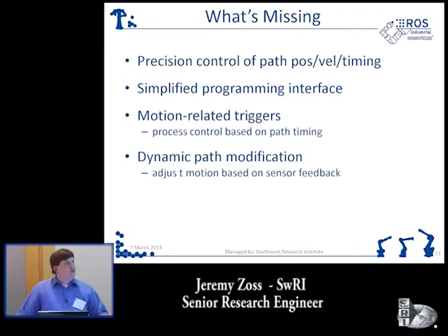You know, there's tools in ROS to really get in there and set constraints, but in some cases, they're kind of buried down in there. On a typical robot controller, it's right there. You say, here's my move command, and I want to move within this close of my termination point, or I want to maintain this velocity, or I want to move around a corner. There's all sorts of specific controls tailored to make sure that you can make the robot follow the exact path that your process needs.